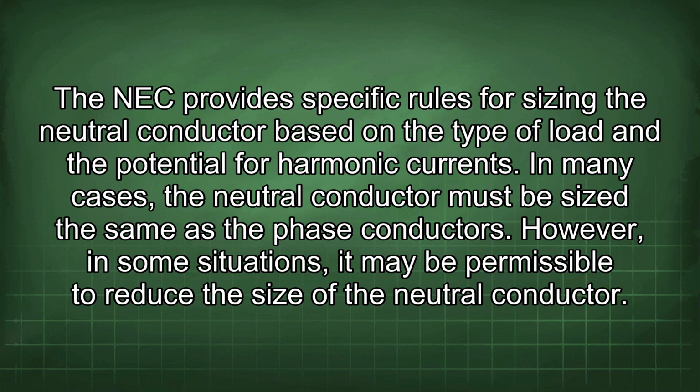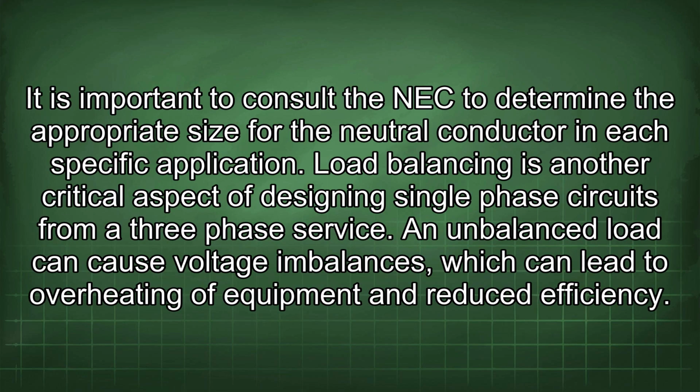harmonic currents. In many cases, the neutral conductor must be sized the same as the phase conductors. However, in some situations, it may be permissible to reduce the size of the neutral conductor. It is important to consult the NEC to determine the appropriate size for the neutral conductor in each specific application.